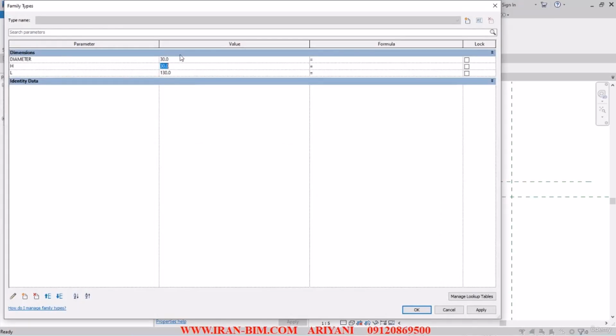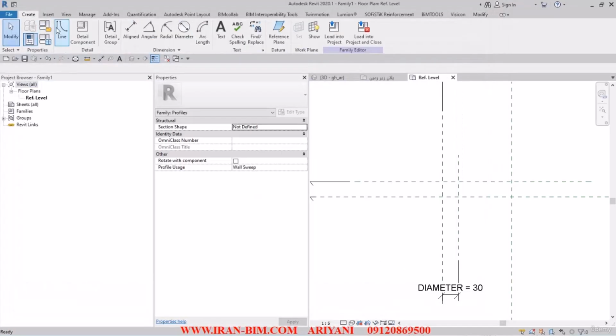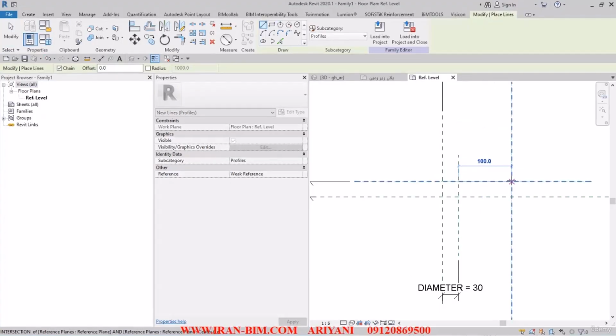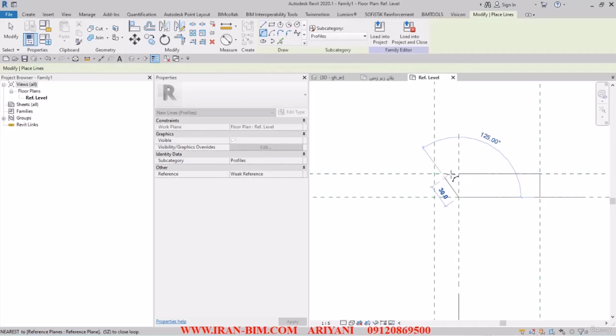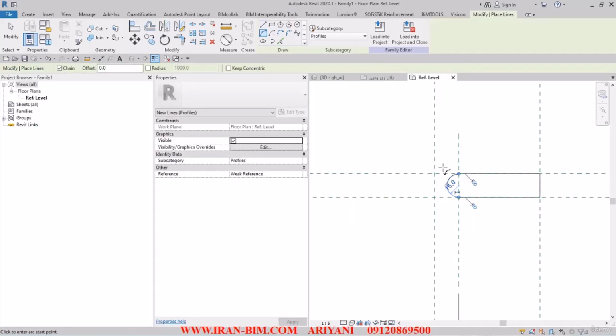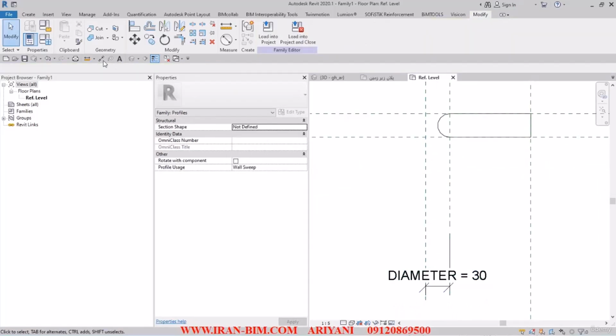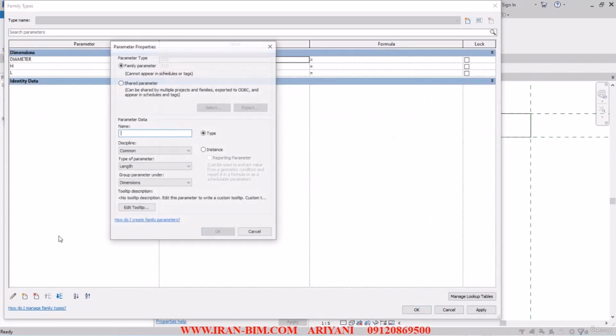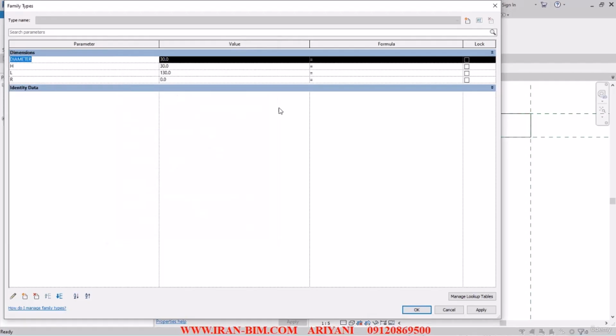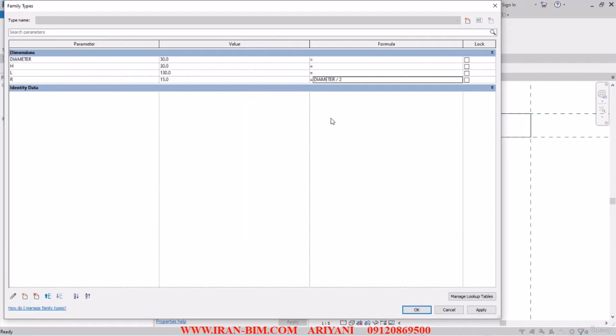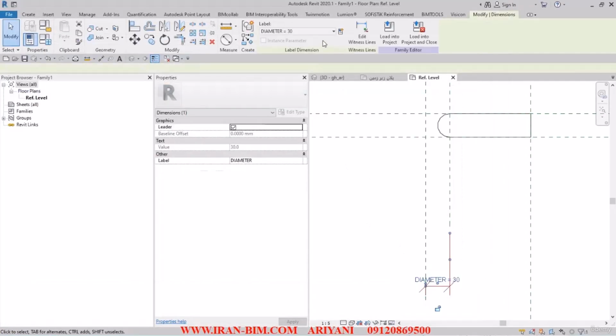So okay here. Then I go to the line section. Then connect this one to this. And then to this again. Then using this, I'll just connect them again. So there we go. And after I've done that, let me just go back to the family types and then I'll create a new parameter and I'll name this one R. Okay. Now here, Control C for the diameter, paste it here and divide it by 2. Okay. And now I'll put this under R.